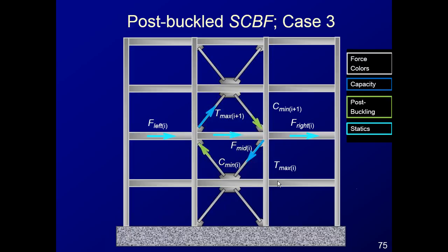So here let's just confine ourselves to looking at the three bays. The three bays that we have here, assume that's the whole building length. Some engineers really don't like to use the full building length, and will say, how many studs can I get into this beam? Can I get 100% of my lateral force from the diaphragm into the beam directly?